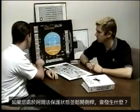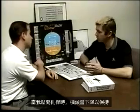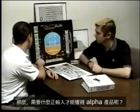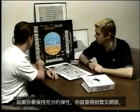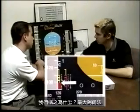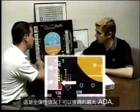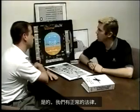We also are limited to 45 degrees of bank. If you're in alpha protection and you let go of the side stick, what will occur? When I let go of the side stick, the nose will fall to maintain the top of alpha prot. So what positive input is required to get out of alpha prot? I'd have to push forward on the stick. If you were to hold full aft stick, you get to the red tape, which we call what? Alpha max. Okay, and what are you commanding in alpha max? That's the maximum AOA that you can get with full aft stick. Okay. Are there any other protections that you find in normal law?